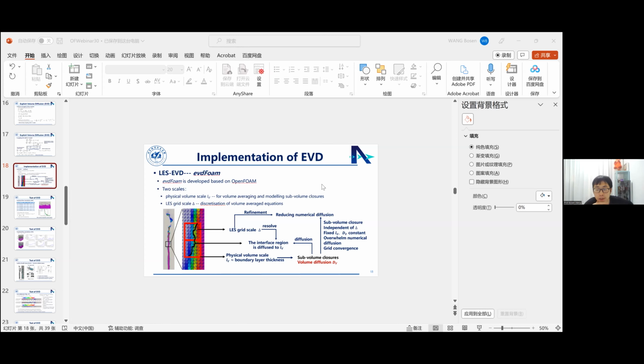Yeah, so to me, it seems like the behavior specifically in OpenFOAM changes between the pure gas phase combustion simulations and volume of fluid simulations, at least in my experience. So usually for the pure gas phase, I get better results with the backward time discretization. And for the volume of fluid, I get better results in OpenFOAM with the Crank-Nicolson scheme. I'm not entirely sure why, but I haven't run that many VOF simulations.